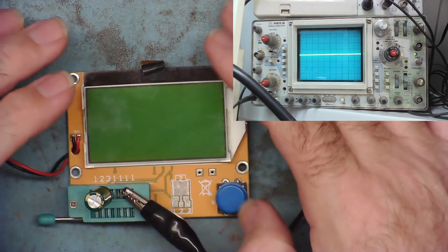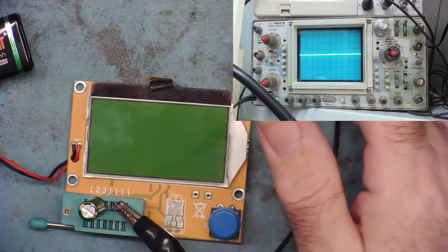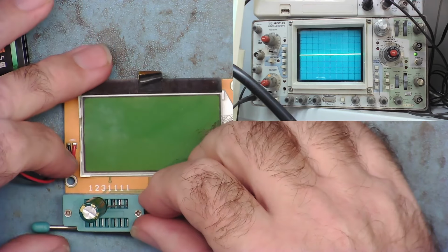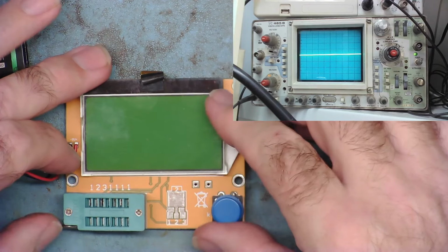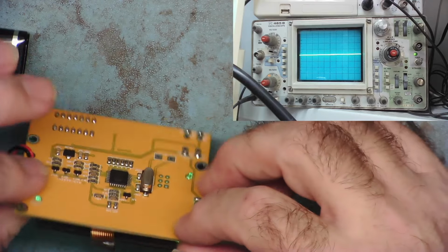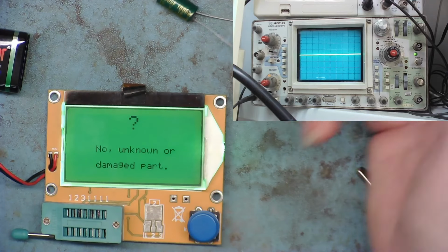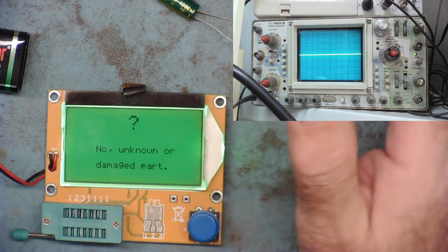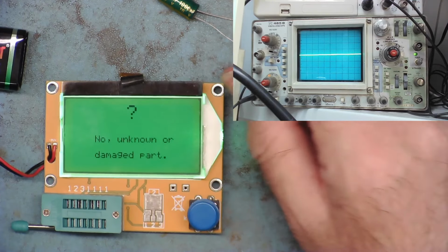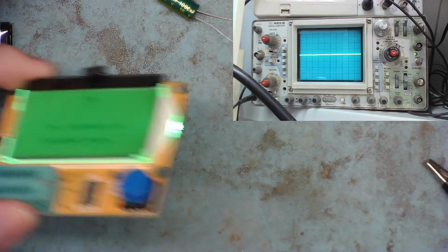So you can't use this in the same way I was using it to measure inductors. You can't use it to find short circuit high side MOSFETs in VRMs, because unless you have a capacitor in it, it won't give you the ESR. It doesn't tell you what the ESR is, yeah? It only does as a byproduct of measuring a capacitor. But as I've just proven, an ESR meter has far more uses than just testing capacitors, if it's a real ESR meter. But you can't call that an ESR meter, yeah?